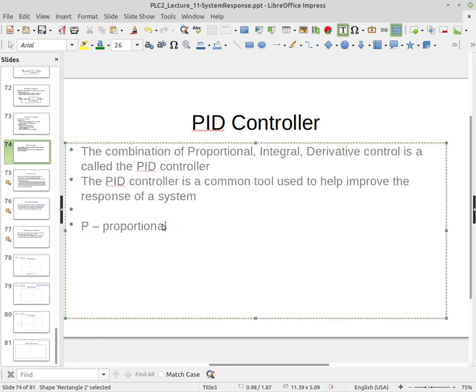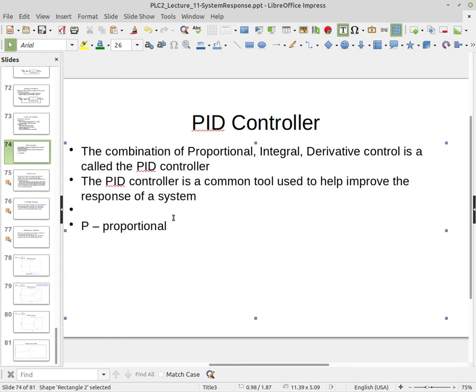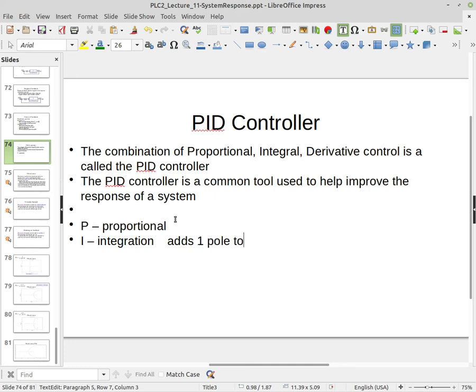All right, so then what we can do is we can integrate. We already did the integrator lab for integrating just to find energy. But what integration does, if we think about the transfer function, is it adds one pole at zero frequency, or DC.